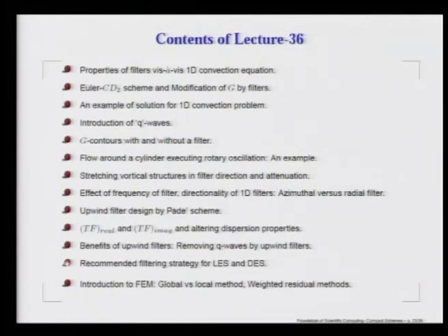We also note that filters can be very interestingly used for large eddy simulation or detached eddy simulation used in fluid dynamics, because essentially filters do band limit the solution, and that is exactly what is done in LES. But LES is far too complicated a process where you actually filter the governing equation, and that brings in newer stress terms which have to be modeled. So, that could be completely removed by the present approach of using these implicit filters as a post processing operation.